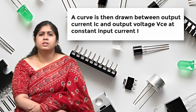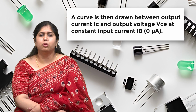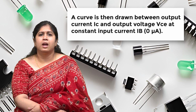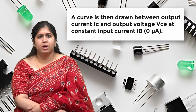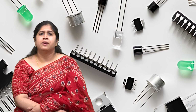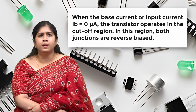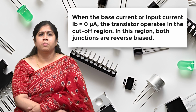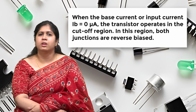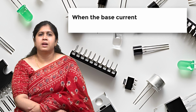A curve is then drawn between output current IC and output voltage VCE at constant input current IB of 0 µA. When the base current IB equals 0 µA, the transistor operates in the cut-off region. In this region, both junctions are reverse biased.